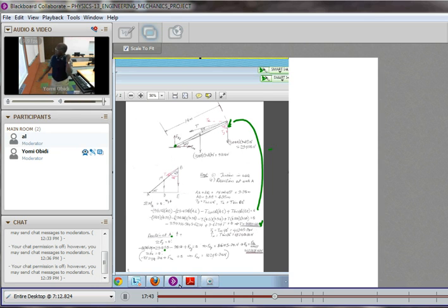And then the weight of the boom itself, which is 9,810, which is that. So all those are forces coming down, and F sub AY is the force going up. We balance the forces, set their sum to 0. That gives us the value for F sub AY.